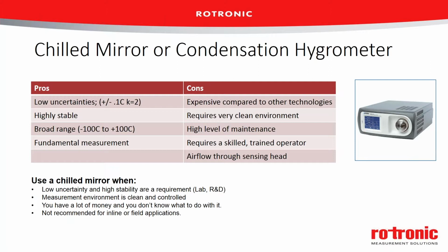They operate over a very broad measurement range. They can be used down to minus 100 degrees C dew point or frost point, depending on manufacturer and configuration, and then operate all the way up to 100 degrees C, again, dependent on the specific model.